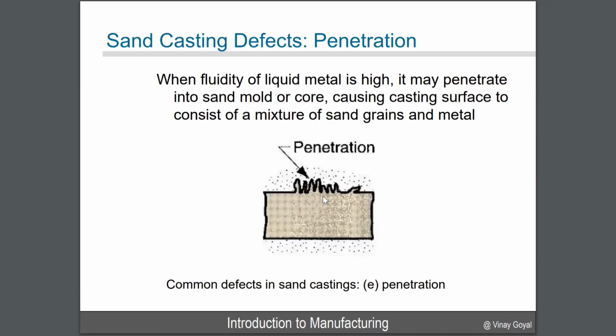Of course, when these defects occur, is the solution usually just to redo the casting itself? No, a lot of it can be fixed. That's a great question, thank you for that. One solution here could be that you machine it to take care of those asperities, right?